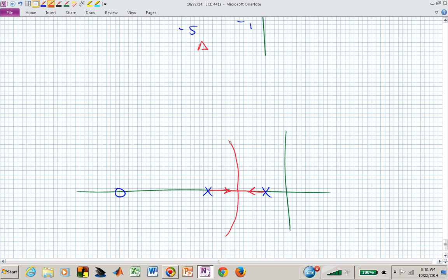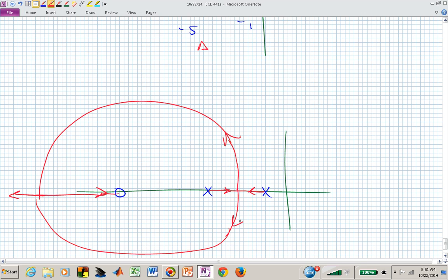That 0 is actually going to be like the center of a circle. One will go back to there, and one will march off to infinity as we crank up the gain K. That's a terrible sketch, but it's sort of close. It gives you the idea. That's what would happen as we adjusted K from 0 to infinity in this particular problem.